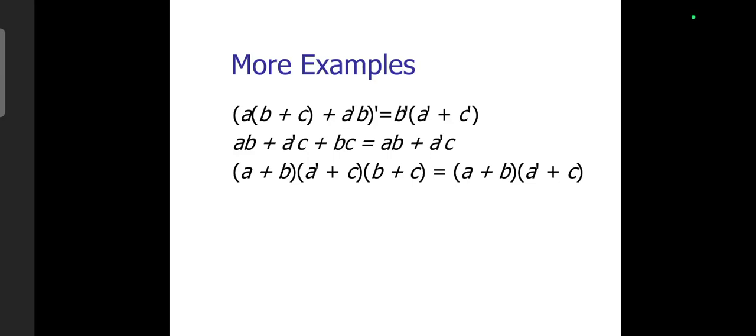For example, consider a factory conveyor belt. A motor may run only if power is available, safety switches are active, and emergency stop condition is absent. Such decision-making process can be represented using Boolean expressions and implemented with logic gates. So Boolean algebra is fundamental to robotics, medical electronics, aerospace systems, and artificial intelligence hardware. In short, almost every modern electronic product around us relies on Boolean algebra in some form.